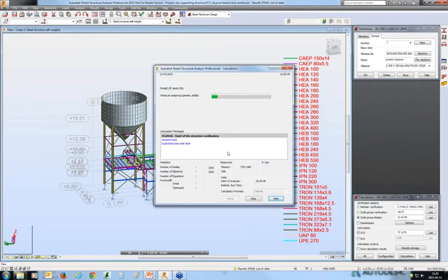The steel design is sort of an iterative process, so you make the assumption, you optimize the sections, you replace the sections in the model, then you calculate the model and check if these new sections are correct, and gradually you just narrow the search for the best sections to a smaller number of elements, and finally all of them are correct.